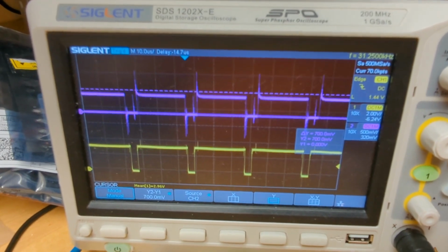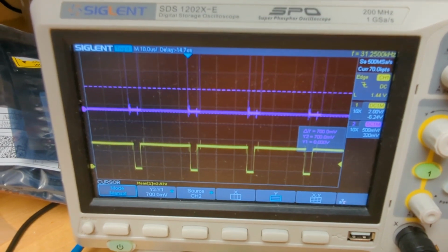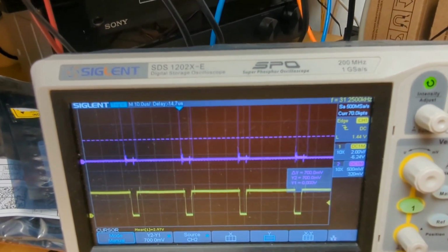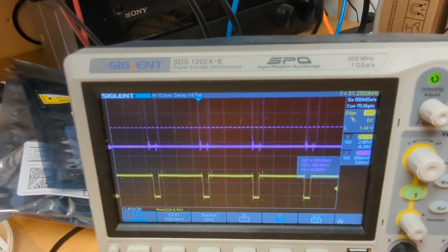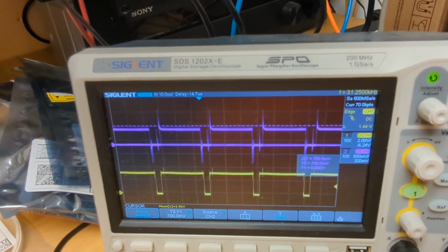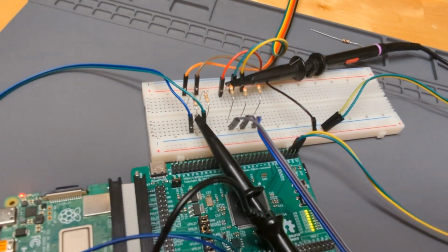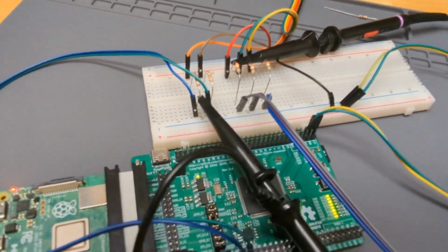If I pull it out all the way, this removes the 75 ohm resistor, and the voltage just went up so high it's not even on my scope anymore. So that's why we see that glitchy noise. And here's me moving it around a little bit. That's how great this breadboard is. Don't buy the cheapest breadboards you can find, is the moral of that story.